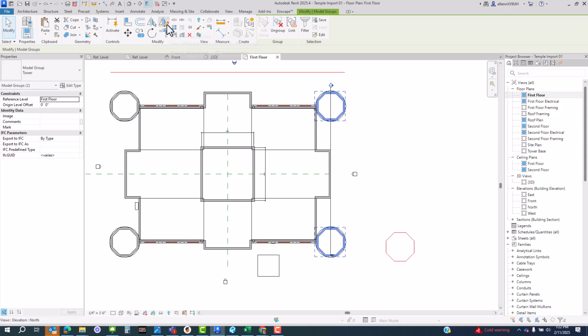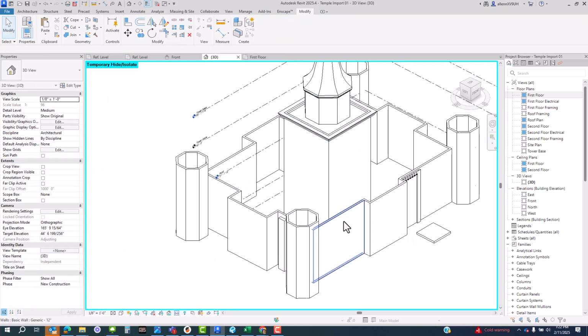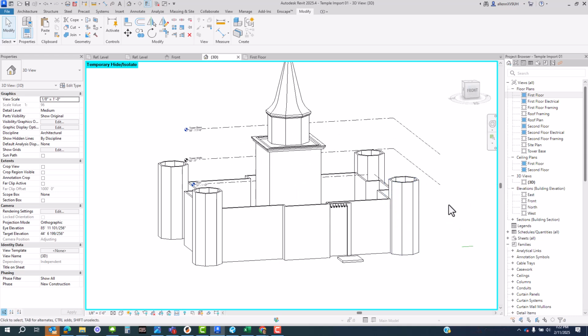If you used this tool, then you get to draw an axis. So you kind of have to know where is the center going to be, but you can draw your axis instead of clicking on something. Okay, well, I've got 4 towers. And now I'm ready to do the roof portion of it, which needs to be done as a family. It's going to be really complicated to try to build that inside of one of these groups. You could certainly try that, but